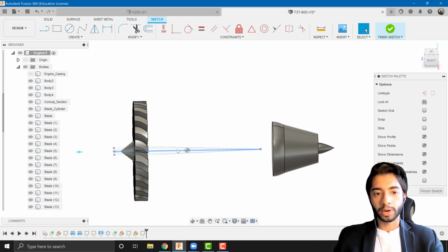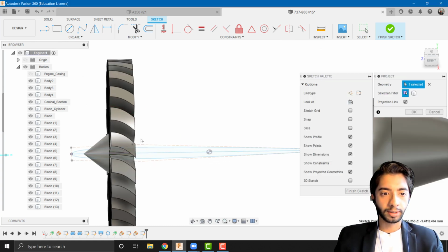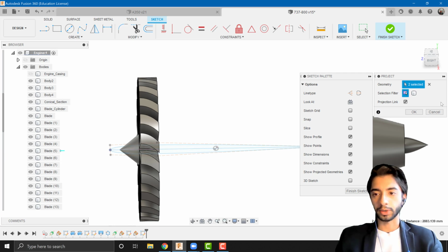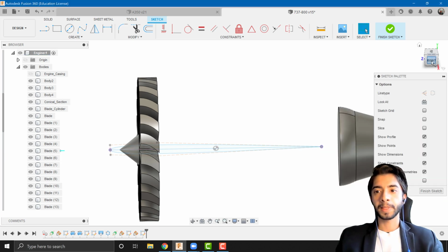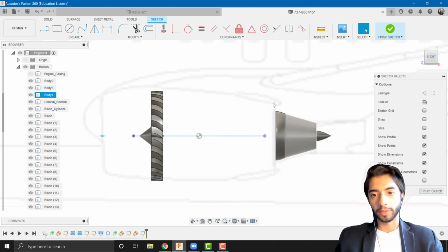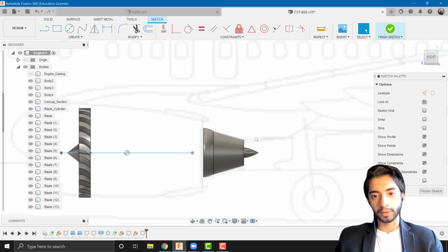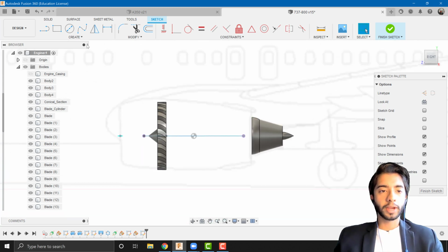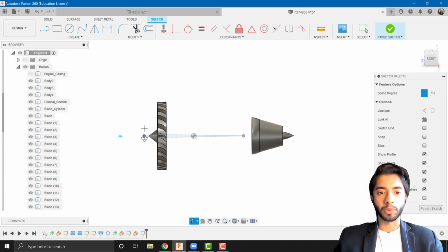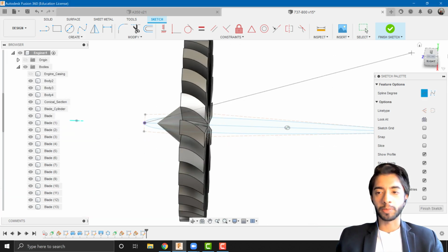And as always, we are going to project the front and the back section of the airfoil. Or alternatively, you could project the chord line. It's equivalent in this case. Okay, great. Now we're going to follow this path. So if you follow my mouse, this is the path that we're going to be creating. So something like that for the front, and for the back, we're going to go somewhere like this. Okay, so if this doesn't make a lot of sense yet, it will in a moment. So let's go to spline, control point spline, and obviously start from that purple section there.